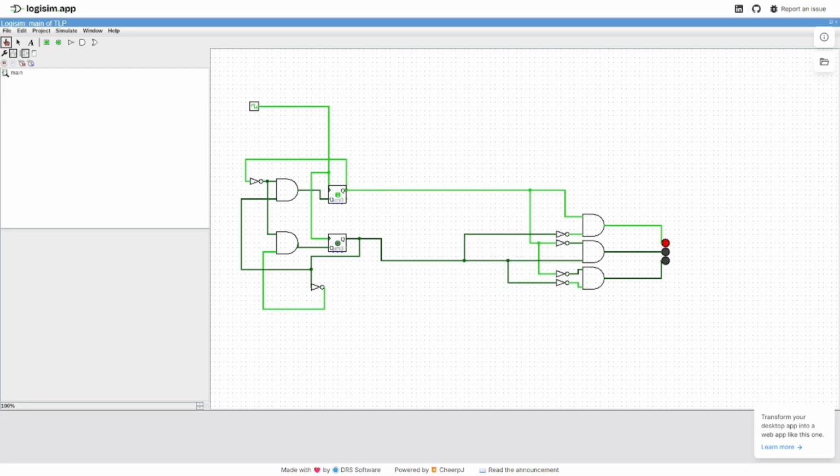Why is there no state where both flip-flops send 1? Simply because D1 and D0, which are the inputs of the flip-flops, will never be equal. We can see that the input of the first flip-flop is equal to the NOT of the output of the first flip-flop, joining the pure output of the second flip-flop to an AND gate, while the second flip-flop has an AND gate with NOT on both of the flip-flop outputs.